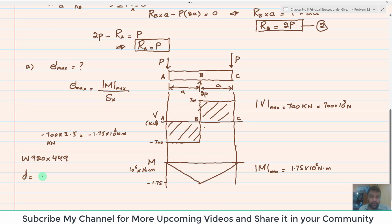D, our total height of the beam, is 947 millimeter. Clear? Breadth of flange is equal to 424 millimeter. Thickness of flange is again given as 42.7 millimeter. Clear? T, thickness of web, is given as 24 millimeter.